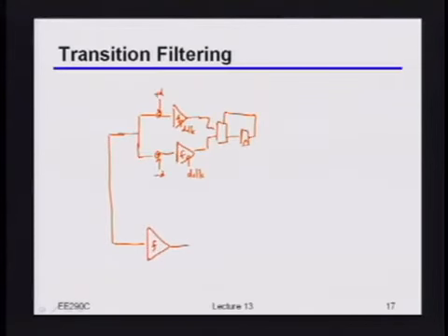But then what you do is you say, okay, I'm only going to use this when I know that I actually had a clock pattern, right? When I know that I had a 101 or a 010, so that I know that timing information is reasonable. And in fact, you can keep extending this to more and more taps. So you can make it so that you only do your timing estimates based off of patterns that you know should have good information, given whatever it is that you were doing in your equalizer. And by the way, you may even want to apply similar ideas even if you were physically closing the feedback loop, if nothing else because when you are physically closing it, your DFE itself may not be settling exactly at the right spot. Does this make sense to people?